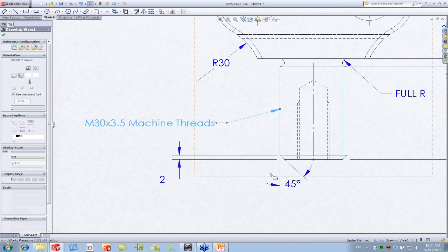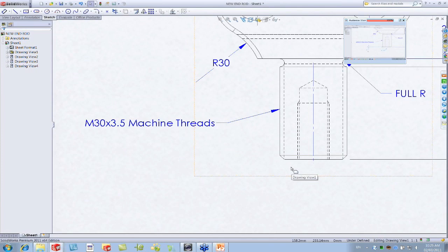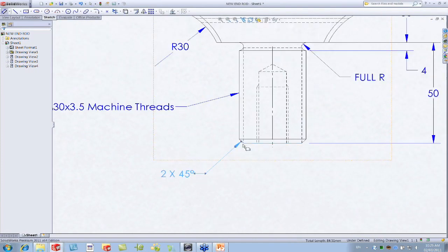So I'm just doing some very quick cleanup activities here. Delete the bottom dimensions here because they are actually a chamfer. I do want to have a chamfer dimension, so we have that in store. So basically pick two edges and drop this little chamfer dimension right there.